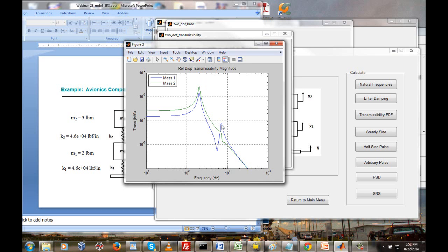And at least for mass 1, we have a spectral peak here at 700 hertz, and the situation is a little more ambiguous with mass 2. It looks like there's some kind of a little jump going on, so I'm not sure we could call that a spectral peak at all. Why and how that happens, I'm going to assign myself an action item to explain to you later.